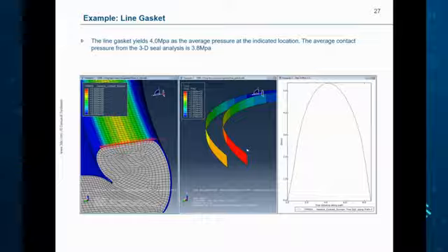The simulation in the middle here seems much less complicated than that full-blown three-dimensional simulation. In fact, you can see here that in the 3D model, just like in the 2D model, I get this creasing behavior, which can be problematic for Abaqus Standard, which is why I chose to run the simulation in Abaqus Explicit. I didn't want to fight with any creasing inside Abaqus Standard. I could probably do that, but in Abaqus Explicit, this is no big deal.